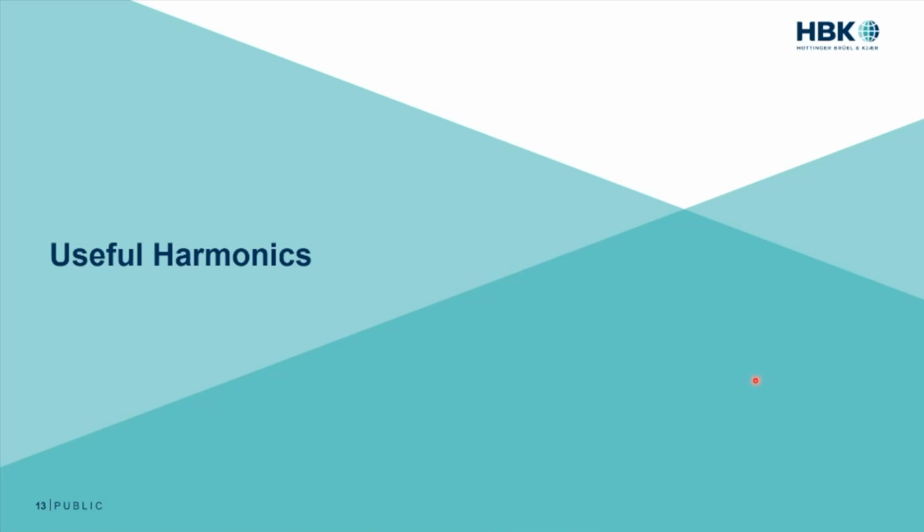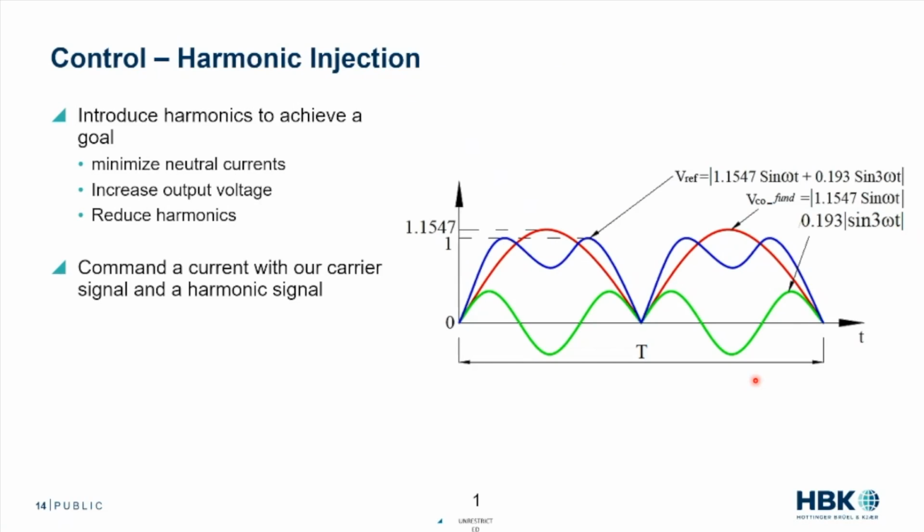All right, so what are some useful harmonics? Well, this is going to come down to a lot of inverter control because a lot of times harmonics are creating losses where we don't want them, but we can do some clever things to control machines with them. So just remember that a lot of these control techniques I'm going to talk about do come at the expense of efficiency and losses. There's only so many ways to fool Mother Nature. We have all these trade-offs.